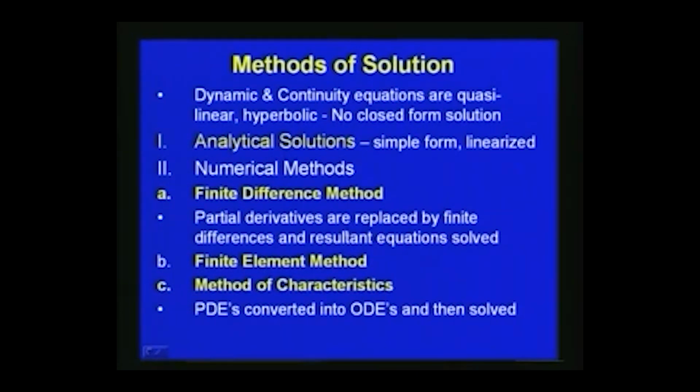We can use variational principles, like the different finite element methods. Actually, this is an integral form: we approximate the governing equation with respect to an interpolation function, then integrate with respect to the system, find the weighted residual, and then approximate. So that is the basic principle behind the finite element method.